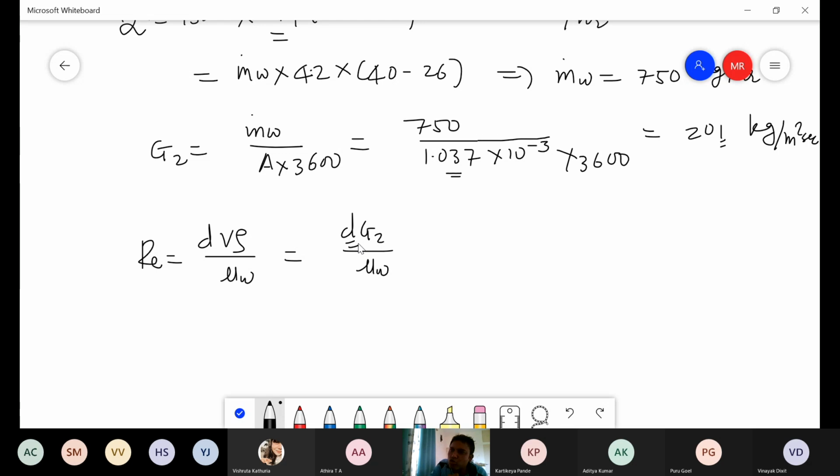See, the flow is now through the annular region. So there is no standard pipe, isn't it? It's an annular region. So for the annular region, we have to use D as an equivalent diameter, isn't it? So this should be DE. So equivalent diameter DE is defined as what? Similar to how we calculate characteristic length. It is something like that, but not exactly the characteristic length.